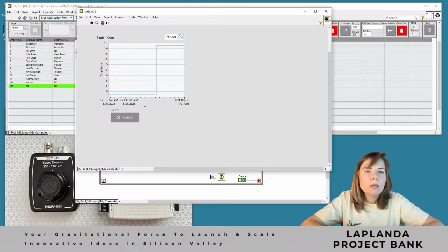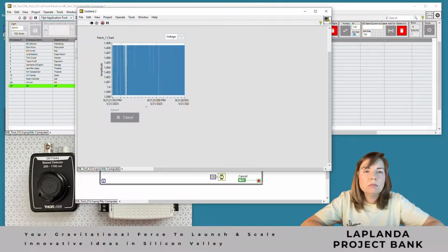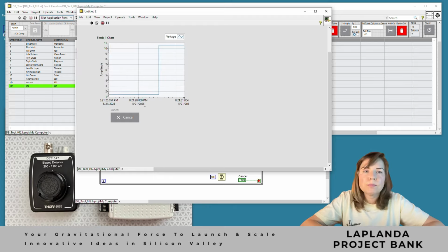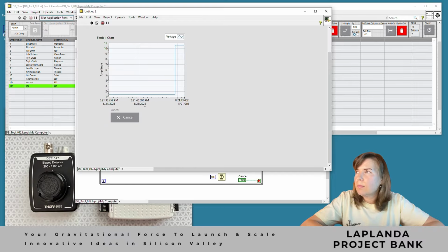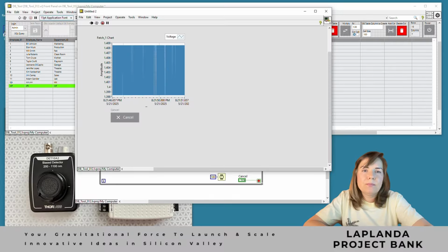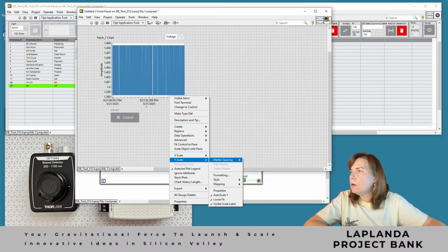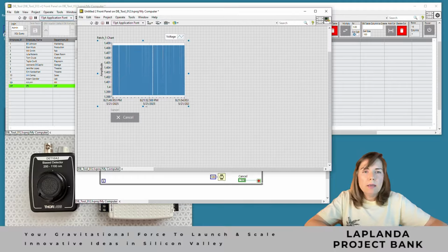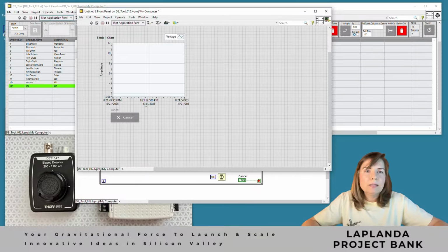I press the red button on the photo detector and we see our white noise. And we see the battery voltage. White noise, battery voltage. So that this voltage jumps on our graph don't annoy us, we'll now disable autoscale on the y-axis and set the voltage range from 0 to 12 volts on our graph. We'll make this state the default and save it.